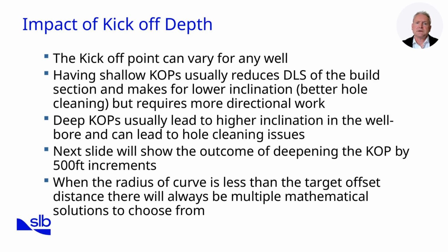Deep kickoff points lead to higher inclination angles and potentially severe hole cleaning challenges. They also increase the risk of torque and drag. Optimal KOP selection balances target geometry, formation stability, and operational risk. For example, formations prone to instability should not be chosen as kickoff point zones. The kickoff point decision integrates geoscience knowledge, drilling mechanics, and long-term well objectives.